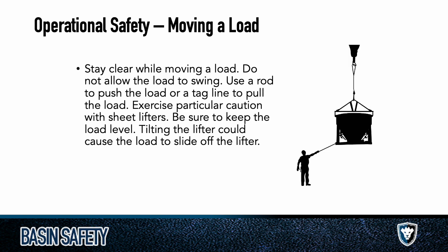For me, it should never be a situation where like 5 foot tag lines, to me, that's no. Obviously the tag line has to meet the industry standard, and you don't want 100 feet of tag line behind you. I can get that. But you also don't want to be barely holding on to this thing, looking like a little kid holding his dad's hand walking down the street. You want to give yourself a little bit of distance so you have control without it potentially yanking you underneath the load. So if you're walking with the thing, you want to have enough distance so that you have some play and you can step around things and have a little bit of rope. So just make sure your tag lines are long enough.